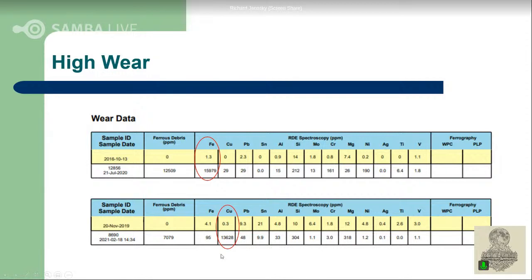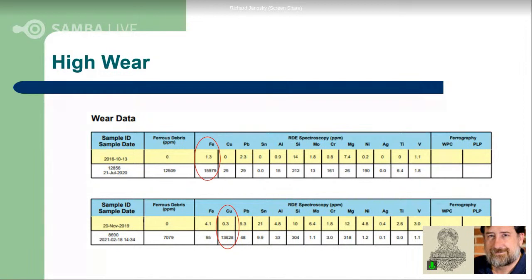The second example we have here is from a main bearing of a wind turbine. So here we see very highly elevated levels of copper. And upon completion of analytical ferrography, we were able to determine that there was a lot of laminar wear, copper alloy particles on the slide, and gave that feedback to the customer, and they went back up tower, and this was relating to a cage issue on their main bearing. So just wanted to leave